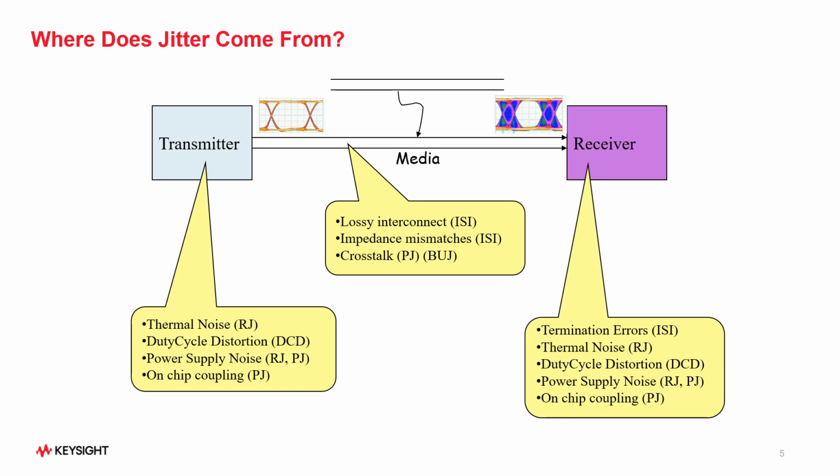As we see, random jitter, or Gaussian, can usually be tracked as a source or transmitter problem. Random jitter can often be the most difficult jitter component to track down, primarily because it is not correlated with the data signal. Duty cycle distortion, or DCD, is another jitter component that is usually considered a transmitter source problem.